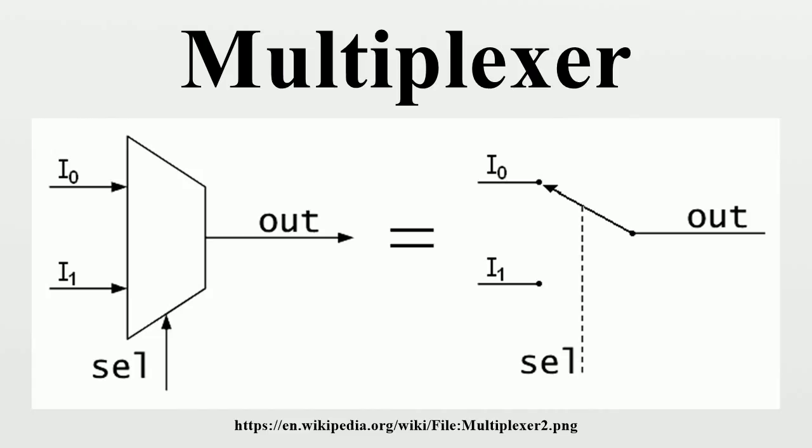Digital demultiplexers. Demultiplexers take one data input and a number of selection inputs, and they have several outputs. They forward the data input to one of the outputs depending on the values of the selection inputs. Demultiplexers are sometimes convenient for designing general-purpose logic, because if the demultiplexer's input is always true, the demultiplexer acts as a decoder.